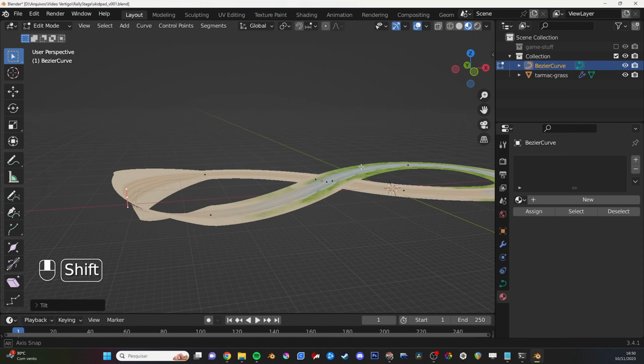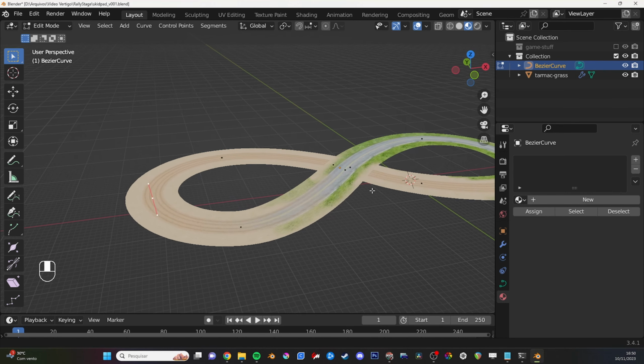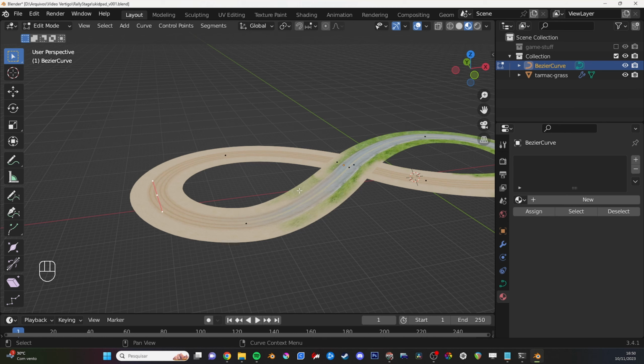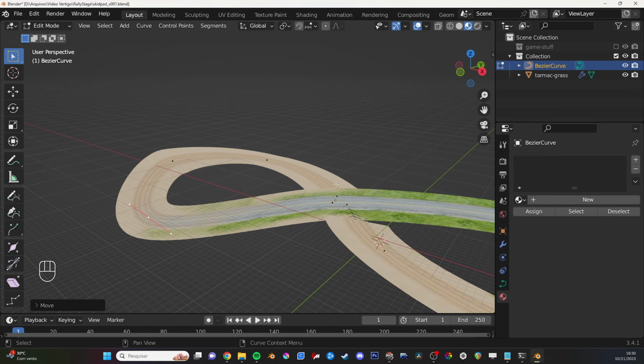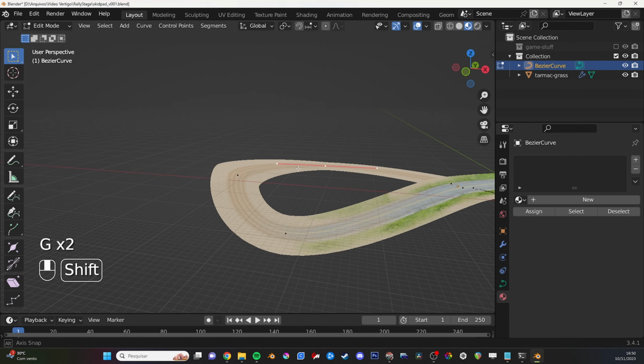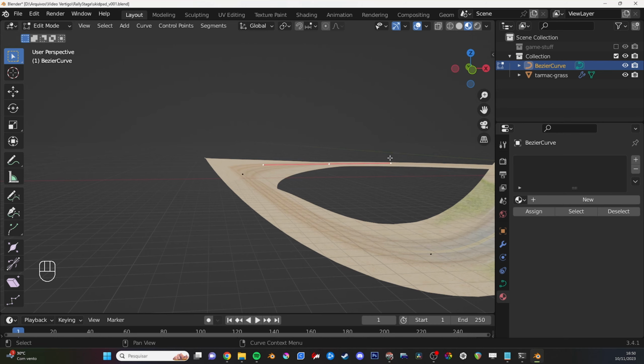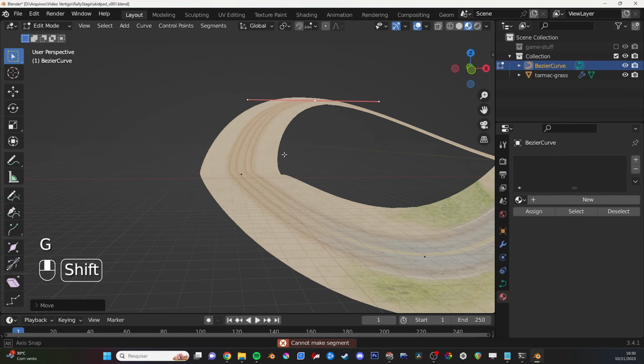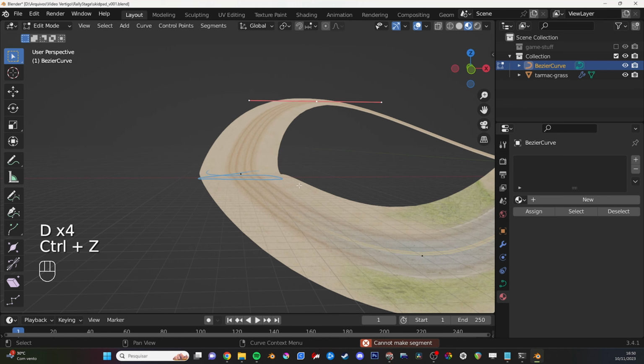There's actually something very important to keep in mind here, because sometimes when you're messing with the tilt right here and changing the rest of the road, you're actually gonna get this effect that is very annoying. Like you go down here, the tilt changes here, you go up, you lose completely the camber you had here.